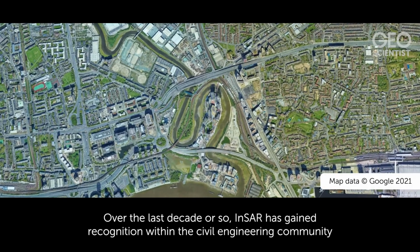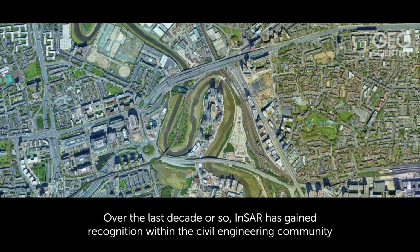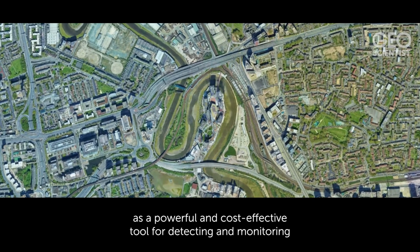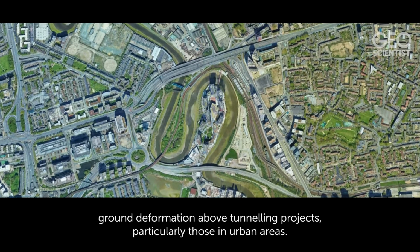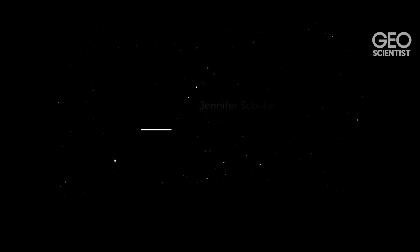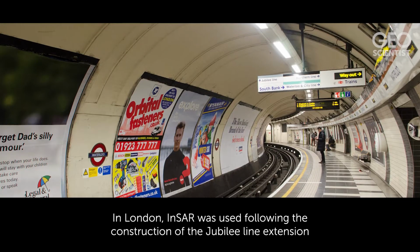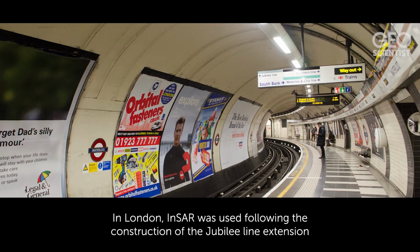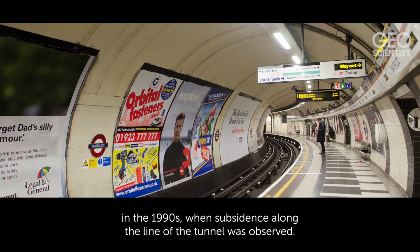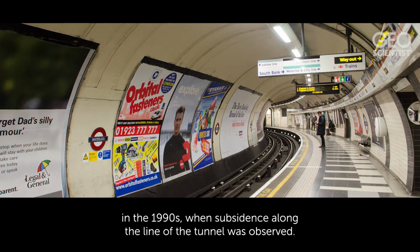Over the last decade or so, InSAR has gained recognition within the civil engineering community as a powerful and cost-effective tool for detecting and monitoring ground deformation above tunnelling projects, particularly those in urban areas. In London, InSAR was used following the construction of the Jubilee Line extension in the 1990s, when subsidence along the line of the tunnel was observed.